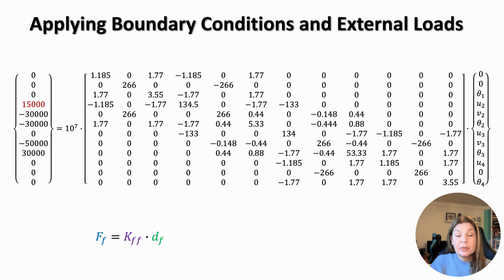So this is the full system before we reduce it. The only thing I need to do here is update the load vector. So in early examples, we only had vertical loads, the uniformly distributed load on the beam and the point load at node 3. Now that we've introduced this 15 kN horizontal load at node 2, it must be added to the corresponding degree of freedom for the horizontal translation at node 2, highlighted in red. That modification ensures that the load vector correctly represents the vertical and horizontal actions on the frame.